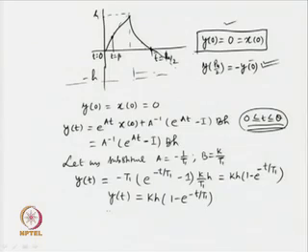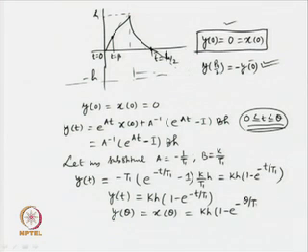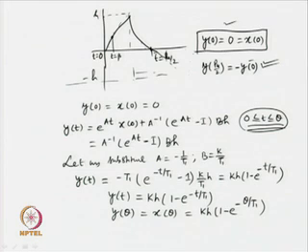So, then y theta is nothing but x theta for us, can be given as k h 1 minus e to the power minus theta upon T 1. So, this is one important expression for us. Why that is so? Because we know that we have a plot for the time range starting from time t equal to 0 to time t equal to theta, during which the form of the output is guided by this analytical expression y t is equal to k h 1 minus e to the power minus t by T 1.